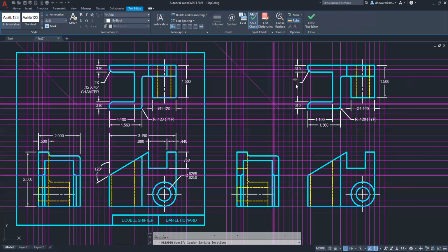And there are two of these chamfers, so that's why we have the 2x, the 2x, return, 0.120, sorry, it should be a 0.120, space x, space 45 degrees. You'll have to go back up to the symbol menu, choose degrees, and then hit return and chamfer.